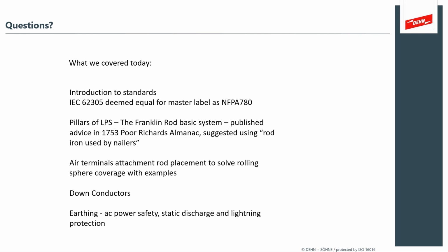Yes, and then we have a question here. What is the best earthing ohm value for a residential project, and the best earthing conductor or material to use for such a project? Well, for a residential system in the United States, National Electric Code, Article 250, indicates that your earth electrode for your AC power needs to be not more than 25 ohms.